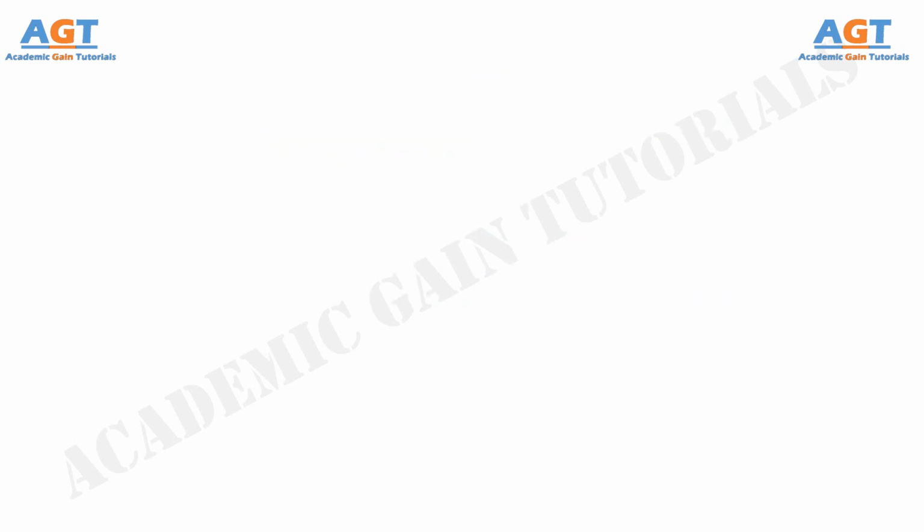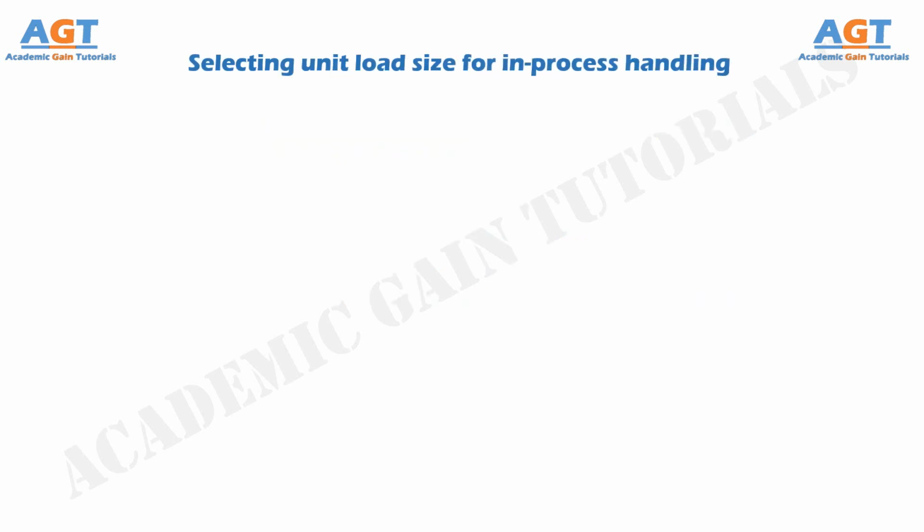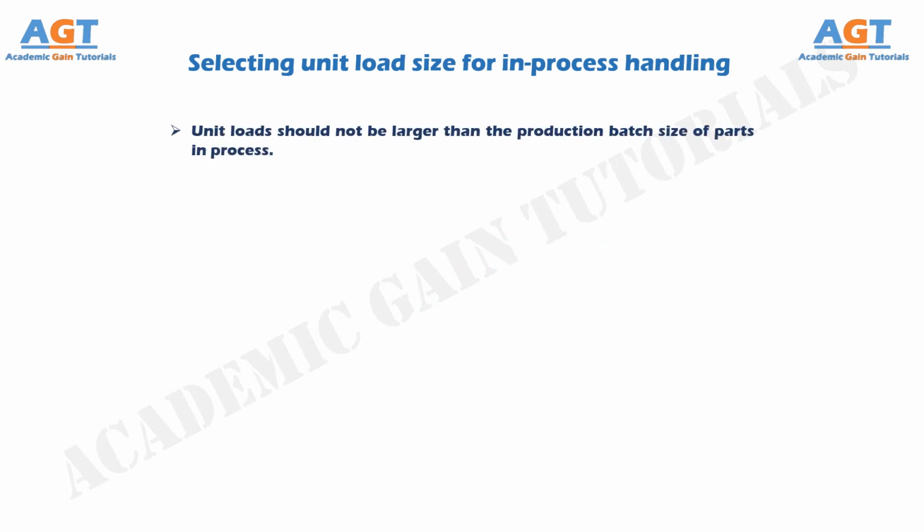Now, let's look at the criterions taken into consideration for selecting unit load size for in-process handling. Unit loads should not be larger than the production batch size of parts in process. If the unit load size is larger, then a delay would occur if the load is forced to wait until the next batch of the part is scheduled to start production, which might be days or weeks, before it can be transported.